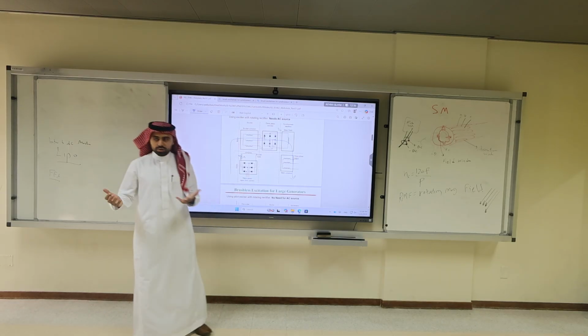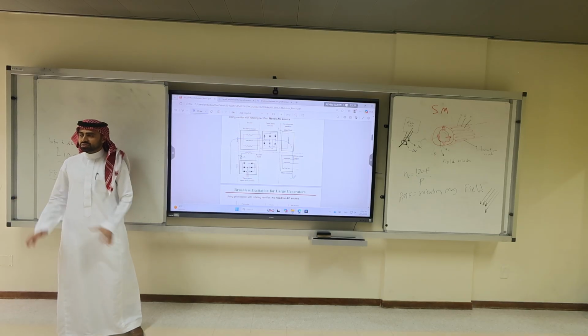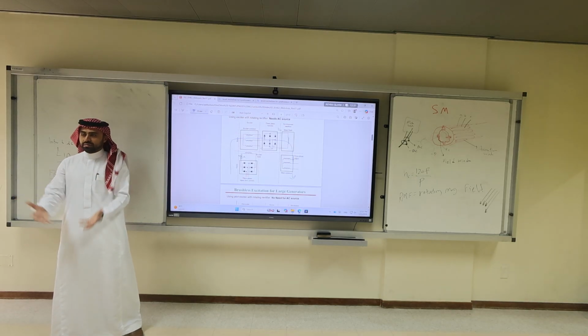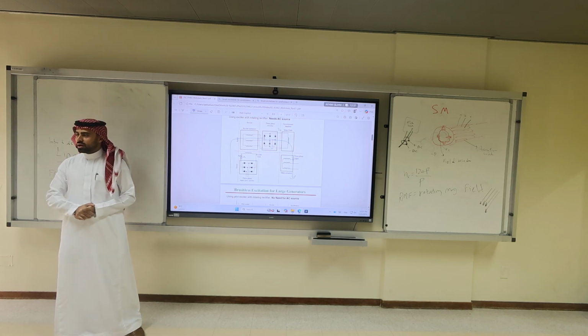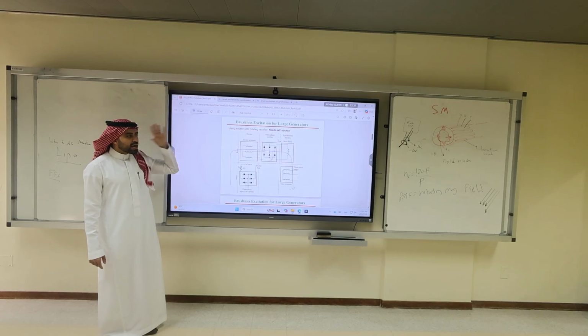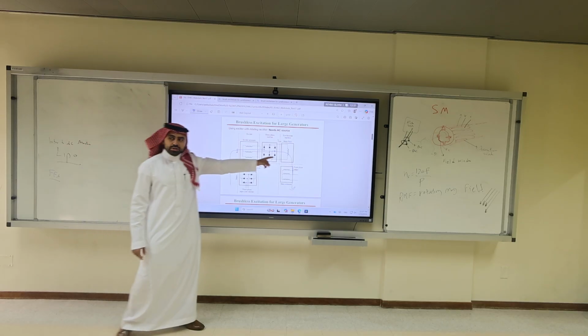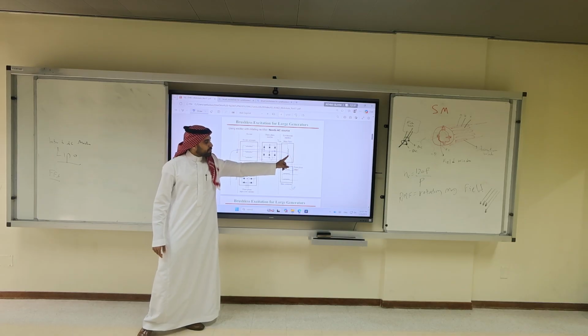Now these are technologies. These are maybe devices that you can buy, or systems that you buy ready. You probably need to put them. So you can buy exciter for your generator. And then they come and they put it for you. Why did we do all of this excitation process? Because I want to solve my main problem. What's my main problem? I want to have a DC field in the rotor. I want this DC to induce the main AC.